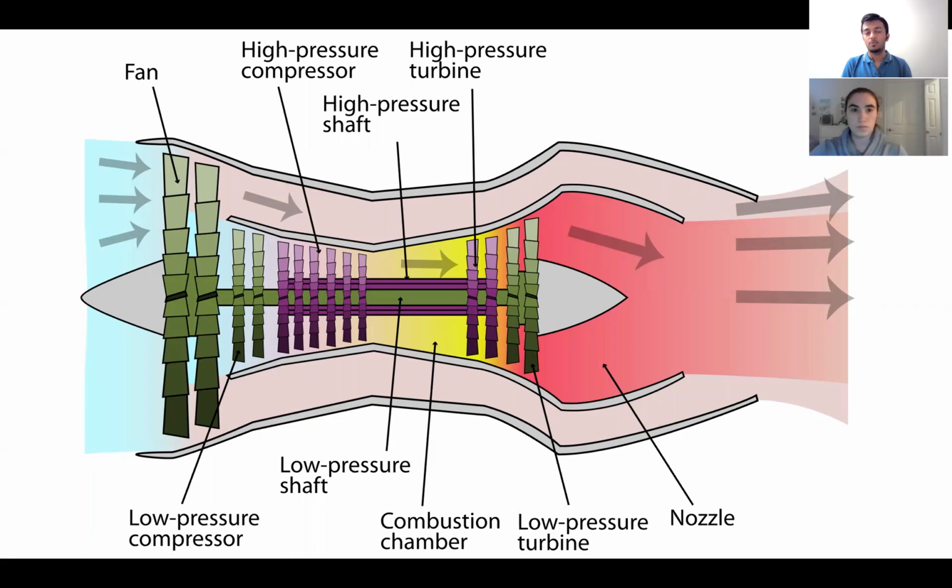So let's talk about what a turbofan engine looks like. In a turbofan engine, you've got one shaft on which you have the main fan, which sucks the air into the engine, and then you've got the compression turbines, and then the high pressure turbines, which compress it to a huge extent, and then fuel is sprayed into that section to combust it using the hot air which has already been sucked into the engine. From the exhaust side, the thrust releases, which creates a reaction in the opposite direction, according to Newton's third law of motion, and that propels the aircraft forward.